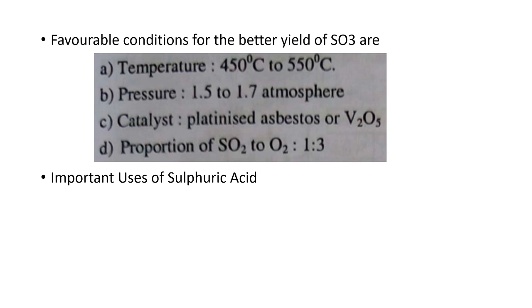That is, platinum is high in cost, but cheaper in the long run. Vanadium's initial cost is low, also cheap in the long run. And platinum catalysts get poisoned by impurities in gases. There is no danger of poisoning in the vanadium catalyst, but you have to take care that at least dust particles and moisture should be avoided. Then platinum catalyst is difficult to handle, vanadium catalyst is easy to handle.